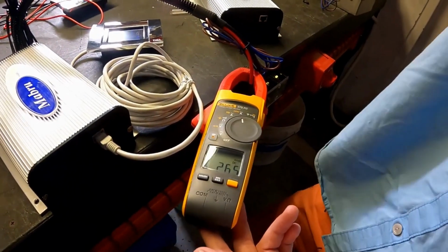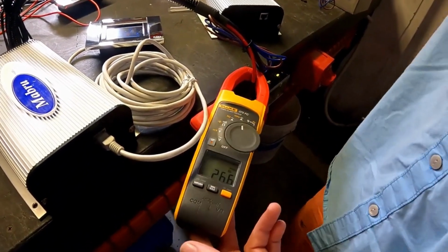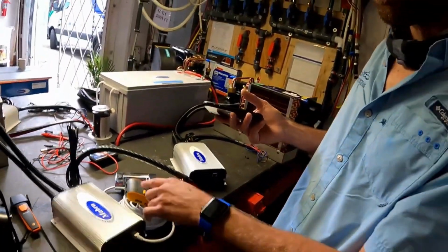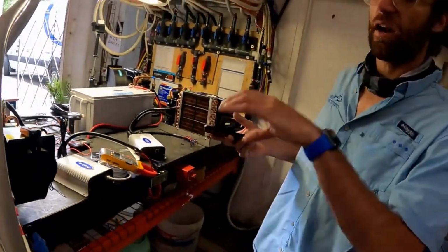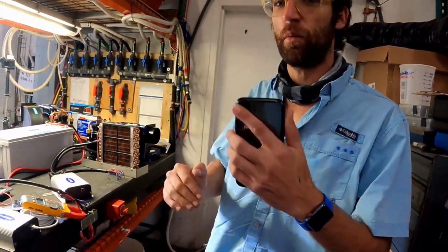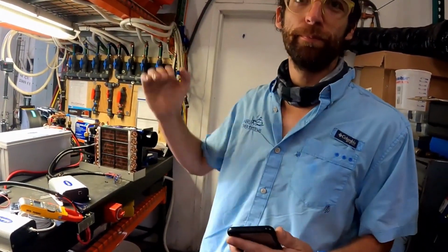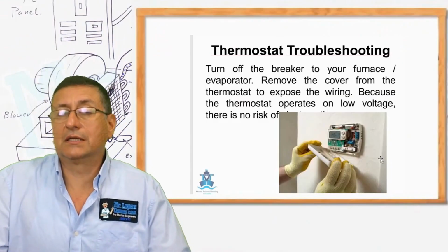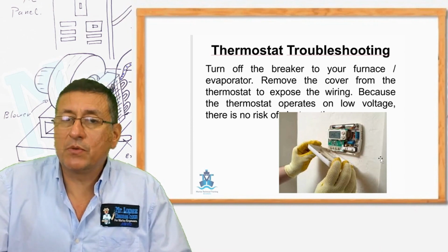It's going to take a little bit of time since it just sped back up again. There are some delays so that the compressor doesn't short cycle. Yeah, that's correct. It depends on the compressor, of course. We really don't want to put too much load on our systems. It just dropped down again, so it just had enough time to switch, but we don't want the compressor speeding up and slowing down. We want it to be very uniform. Correct. Okay. Yes, those are the most common thermostats used in marine applications.